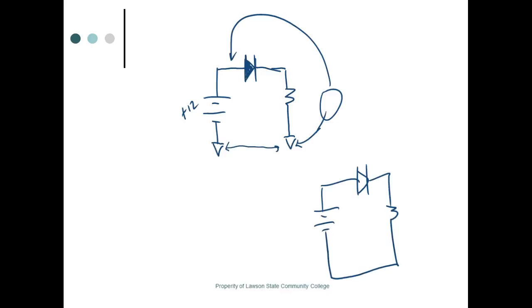We try to prevent putting a voltmeter inside a circuit, because then you're measuring across, right? You understand. So normally, when you see all these calculations, they're going to be relative to common. That way you can get an alligator clip. Most meters come with a nice alligator clip, and you find a good common, clip onto it, and then you're probing with how many leads? You're probing with one lead, which makes it extremely less dangerous.